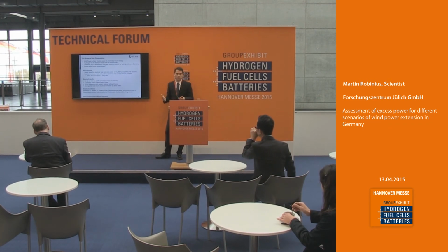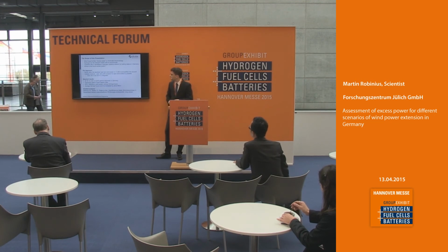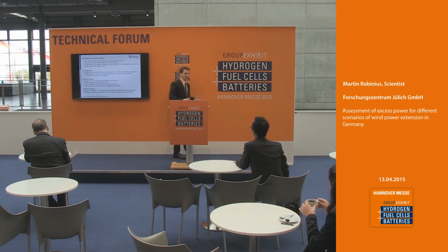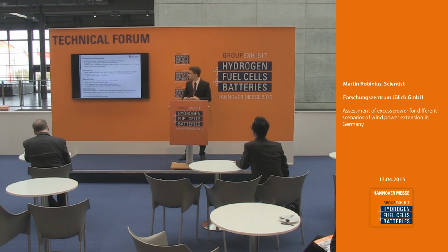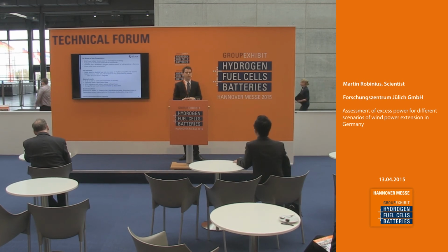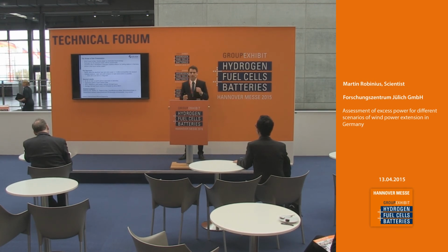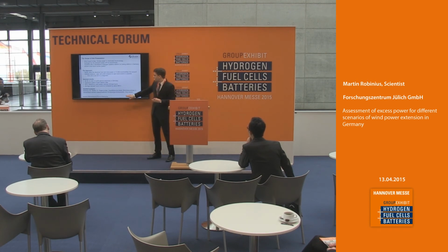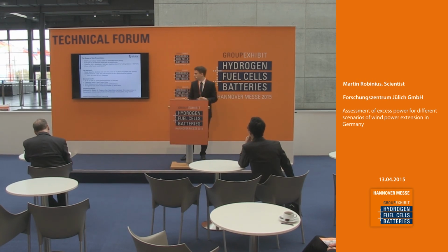Furthermore, I showed you a few selected results. If you are further interested, you can go to the published work or even to the presentation. And what we can see is that in Germany there wasn't so far a cost- or profit-optimal installation of wind power. It was more driven, for example, by the goals of each federal state, not by a cost-effective installed capacity. We have the regions nearly only in the north of Germany, because there we have high wind speeds and a lot of full load hours. If we would install a future system driven only by full load hours, we could increase the full load hours by about 800 hours.